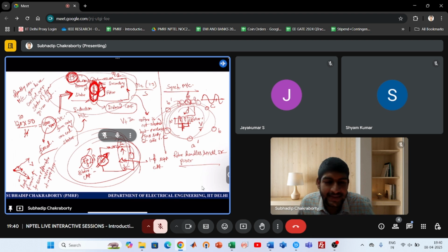So as you know, the generators or the alternators in a thermal power station are also connected to GTs, the generator transformers, and then they are passed to the transmission line. So you obviously want to operate the generators at a better power factor, because if you don't, the currents will be large and almost all the power that you generate or sell to the power grid will be lost in the form of I square R losses.